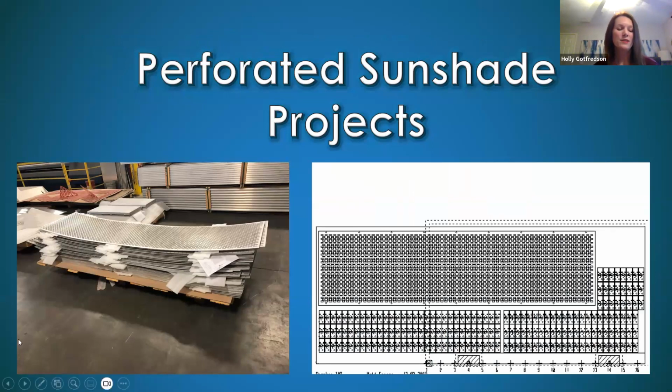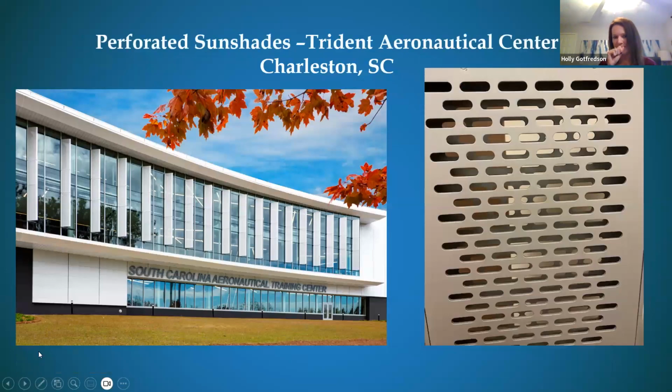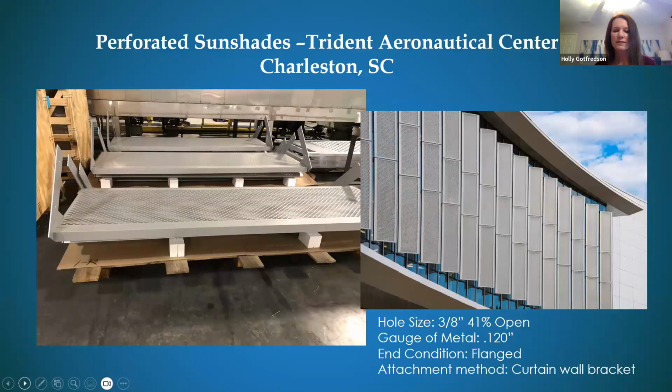That's another great way to stave some energy off the building and also create a nice focal point for your project. In this instance, we did some vertical fins on the South Carolina Aeronautical Training Center. It creates a little bit of shade for the occupants, but it also looks really nice and creates a focal point there. So you can see those in production on the left and then the finished product on the right. An attachment method there was to the curtain wall bracket.